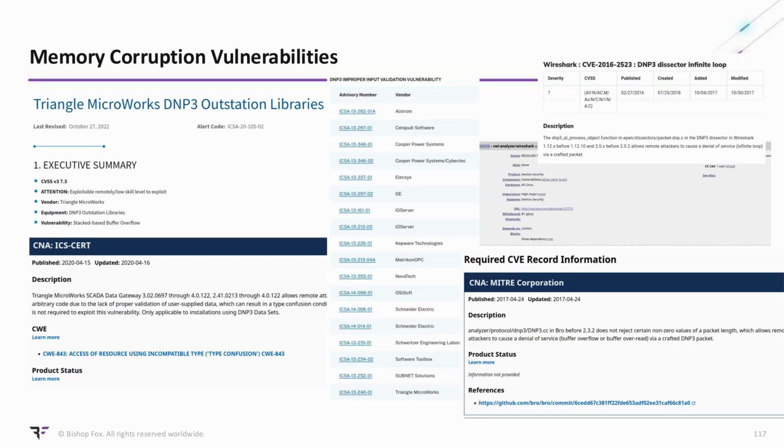These are just a smattering of memory corruption vulnerabilities that you can find if you just Google for DNP3 CVE. Now, the world is filled with many, many, many implementations. All kinds of devices made by all sorts of manufacturers, and they all share this in common. In fact, the two on the upper right aren't even RTU hardware. Those are the Wireshark dissectors for DNP3. So even the hackers who tried to make a Wireshark dissector couldn't get it right. So that's a thing too.